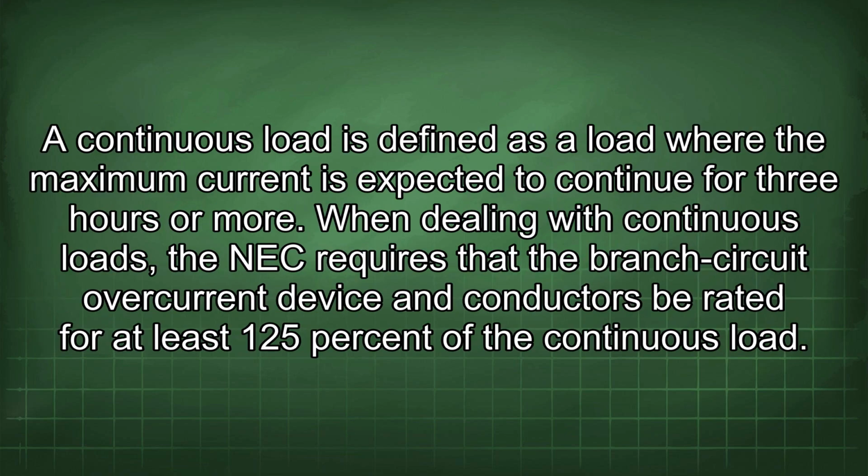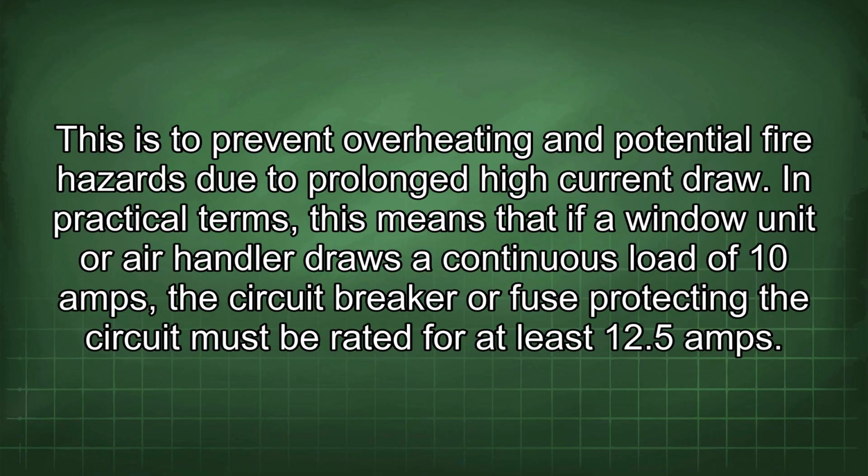A continuous load is defined as a load where the maximum current is expected to continue for 3 hours or more. When dealing with continuous loads, the NEC requires that the branch circuit overcurrent device and conductors be rated for at least 125% of the continuous load. This is to prevent overheating and potential fire hazards due to prolonged high current draw.